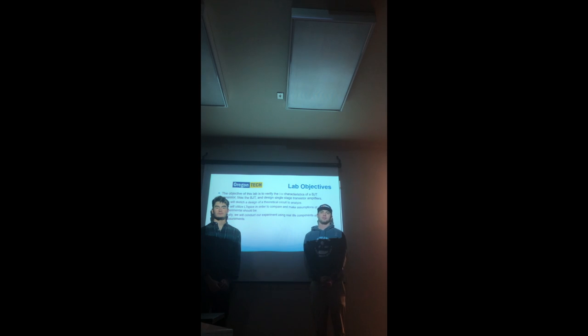We will use LTspice to design a schematic and test the bias points, test the gain, test the frequency response, and test how temperature will affect the circuit. Finally, we will conduct our experiment by putting our design on a breadboard and testing to find our results.